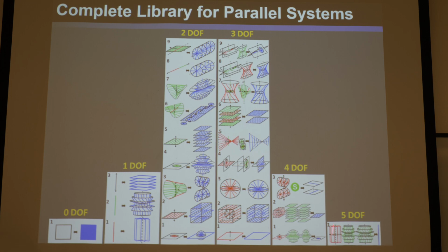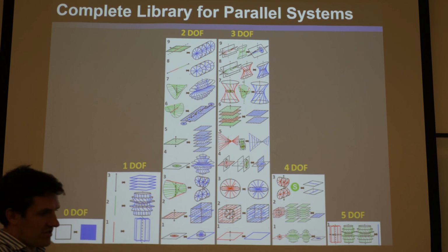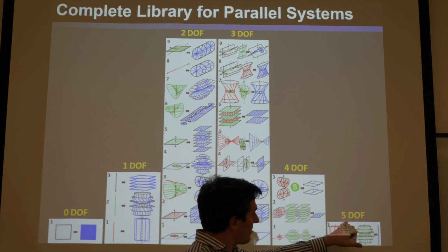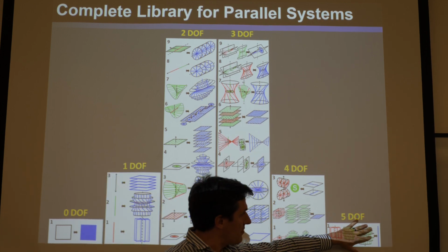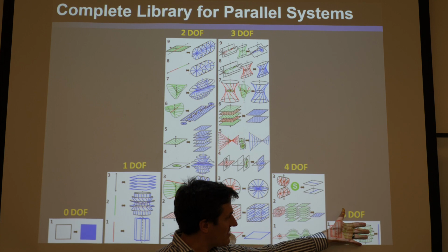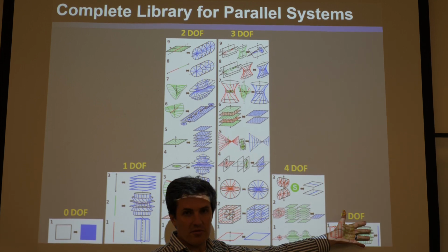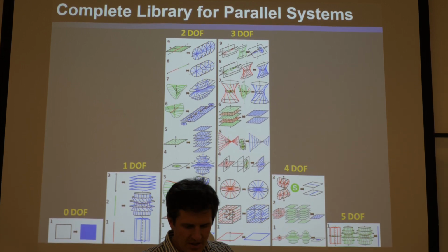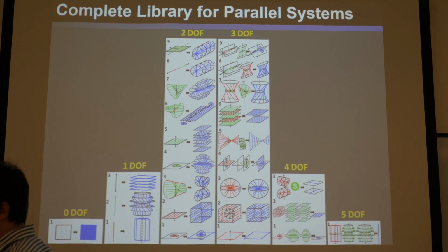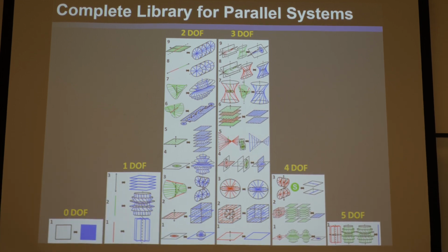But there's not going to be another freedom and constraint space type in case one, meaning where you have a single wire, and therefore 6 minus 1 independent wire is 5 degrees of freedom. So in the 5DOF column, there's just one. So my whole point in this is, well, one, to give you experience with this, but also to prove to you that there's just one type in the 5DOF column.